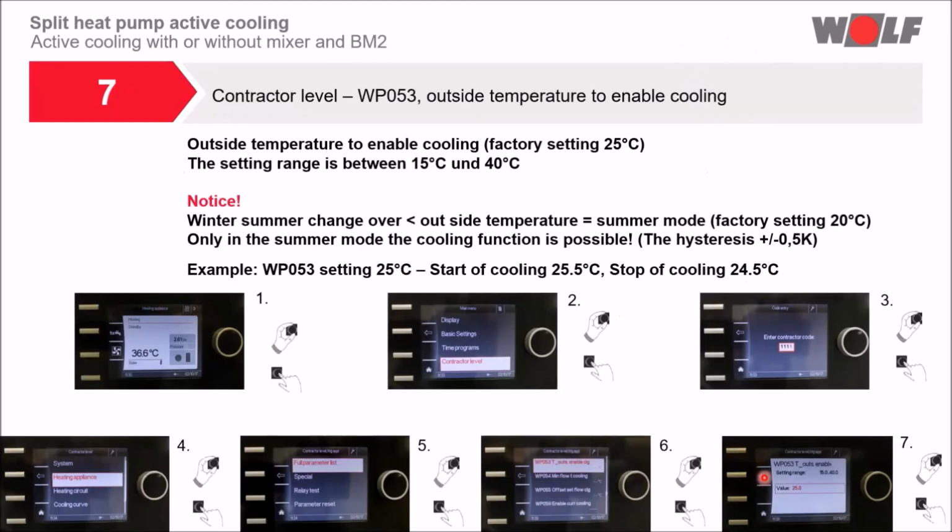The active cooling is activated with the parameter WP53 over the set outside temperature. Only the outside temperature is able to start the cooling function. That means the appliance mustn't be in the heating mode.